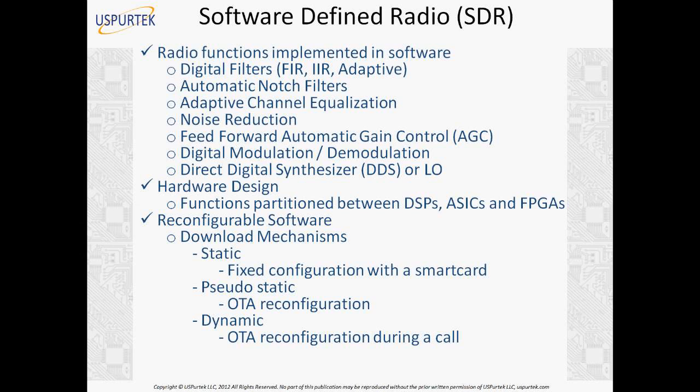Transmitters will have PLLs to stabilize the RF oscillator frequency which is transmitted, so that you can maintain your carrier frequency at a fixed point. It doesn't change with time. It doesn't drift with voltage. It doesn't drift with temperature. If there is a drift, it's fixed. It's automatically taken care of by providing a feedback loop.